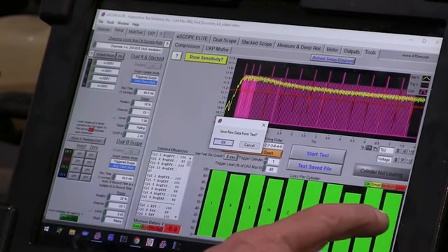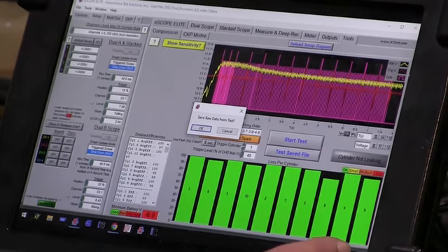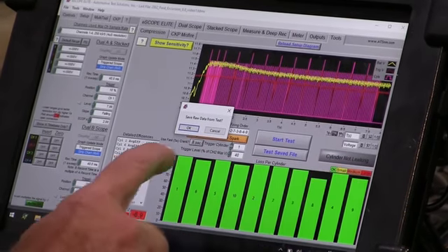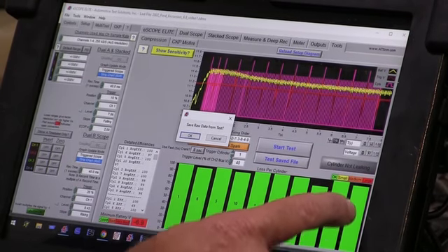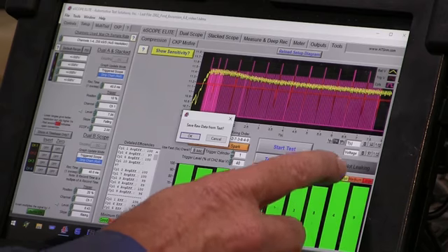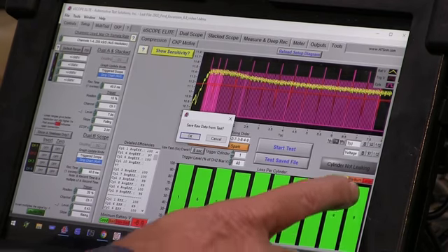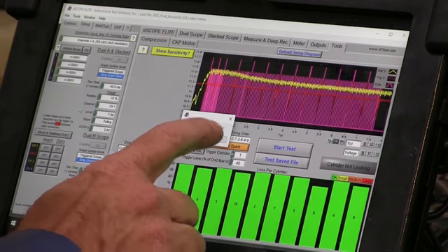Okay, there's no low cylinder here. They're all good, and the one I'm mainly concerned with is 9, and I've got really good compression. So I do not have a compression loss, and we know that 9 has turbulence cranking wide open. So we just did a test with it wide open and we had heavy turbulence. So I'm going to tell you this isn't leaking. That's what that's going to tell me.